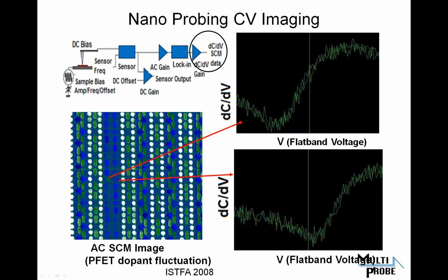So the thing I want to focus your mind on first is this image, and where the beginnings of these arrows show up. You'll notice a small contrast difference between one that's green and one that's blue, right next door neighbors to each other. These two devices, or the devices underneath those contacts. Again, we're looking at an SRAM array that's been polished down to contact layer and scanned with a capacitance microscope, and we get this anomalous image contrast. So the question is, what is the image contrast between these two contacts?